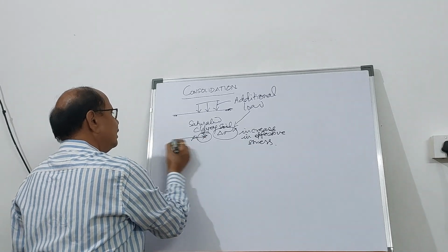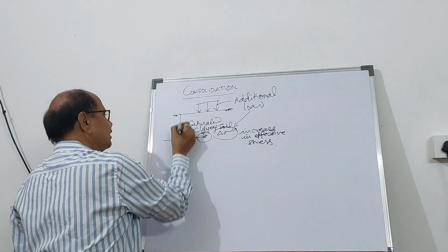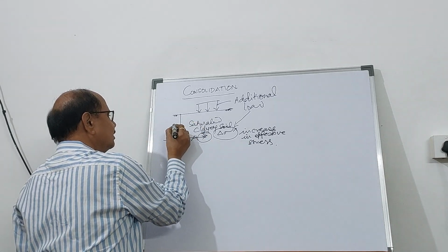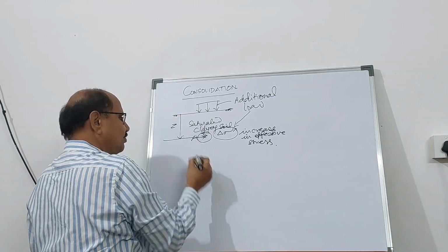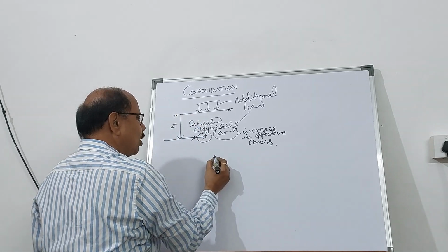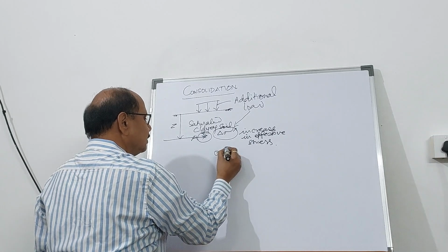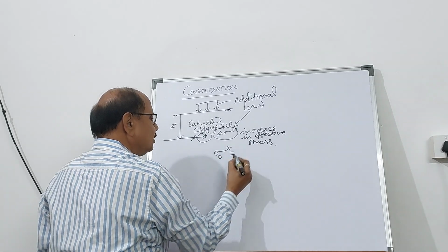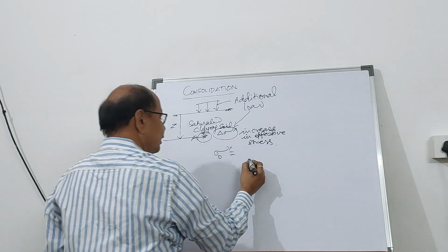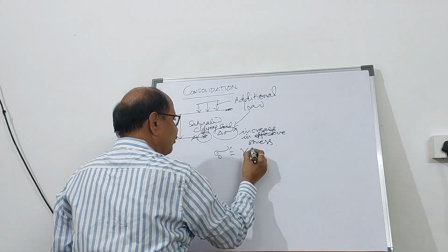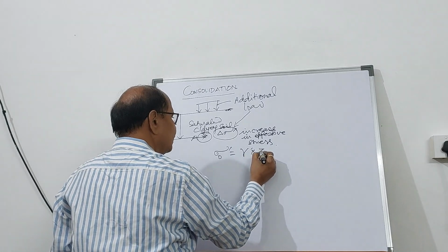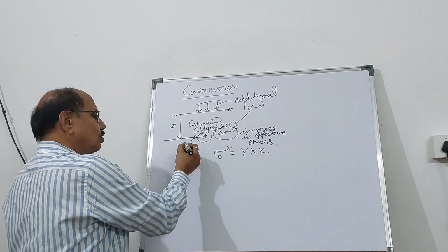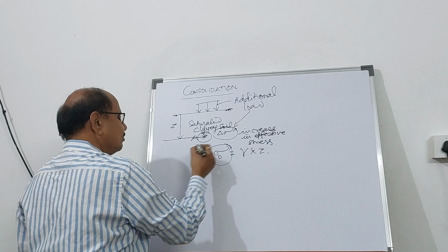And this point A is, say, at a depth Z from the surface, then at this point the effective overburden pressure is going to be the effective unit weight of the soil mass multiplied by Z. So already this was existing.